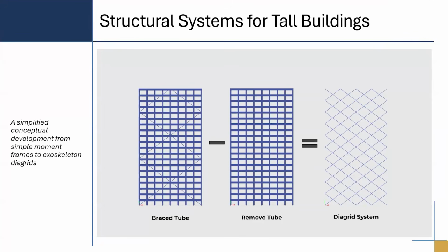One is based on bending, other is based on axial load. One thing I told you before in the previous course, tension compression. If you can avoid bending by any means and convert the things post-transfer into tension compression, it will always be more economical than bending shear. So all of these systems are trying one basic thing: reduce bending, reduce shear, convert to tension compression. That's the end game. As long as you can do that, your system will be efficient.